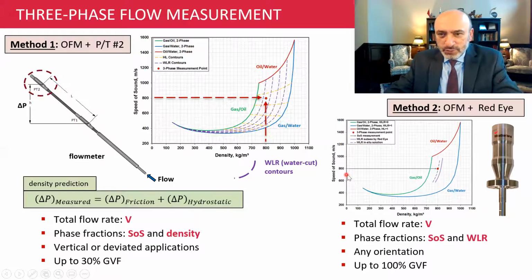Now, in terms of solution, again, instead of density, we are measuring speed of sound and the water cut. So we are actually reaching our three-phase flow point. And once we get that point, we can also calculate the density and liquid volume fraction.